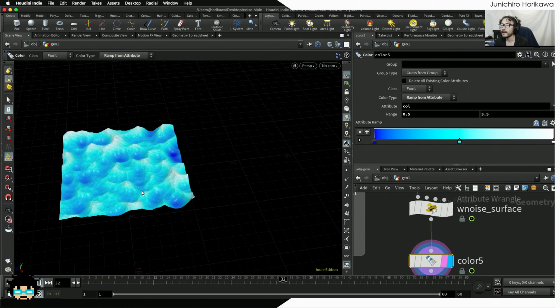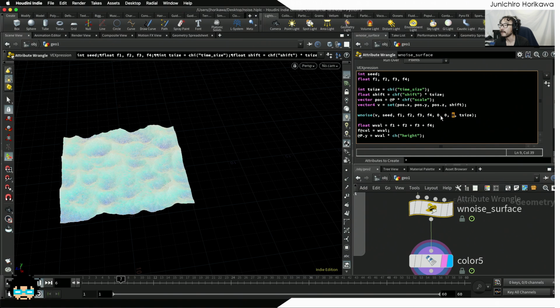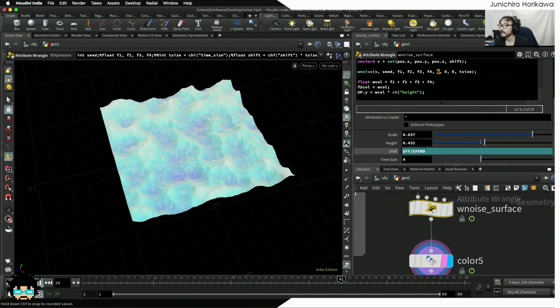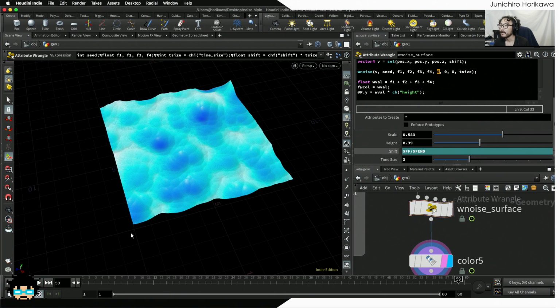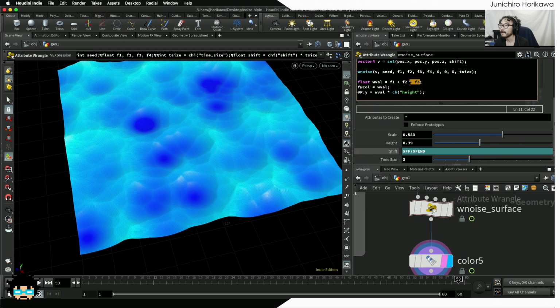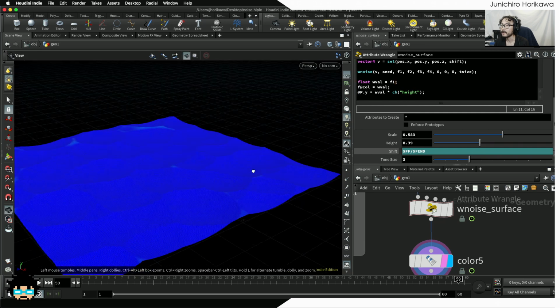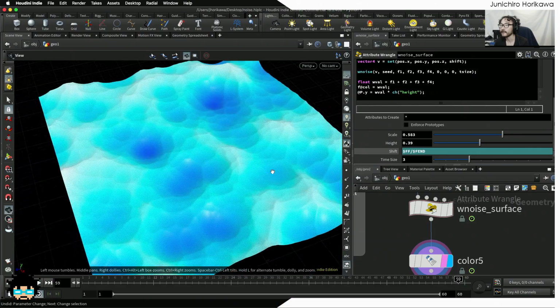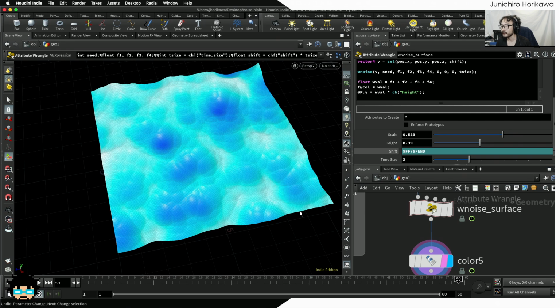And if you want to make it bigger and make it repeatable, you can create this surface repeatable by setting the repeat size or tiling size right here instead of 0, which is pretty useful, I think. Okay, which creates a really interesting surface like you see here. Alright, now if you remove one of the values like F4, it will create a simpler surface like this. If you delete this one, it creates a simpler one. And if you have just F1, it becomes more like a Voronoi surface. By adding all these together, you have more detail for this cellular noise value, which gives you a really interesting surface. Okay, so that's how the Worley noise can be used or works.